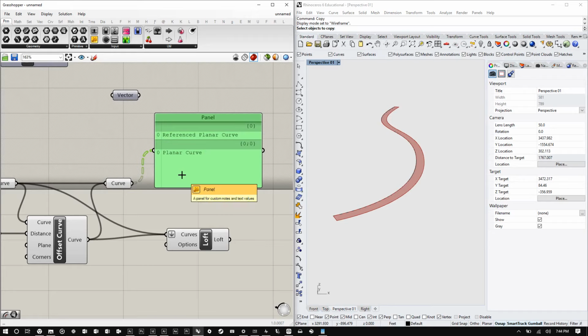And right now they're in a grafted state. So all data trees can either be grafted, which means each object is being treated as a separate individual object, or they could be in a flattened state, which means both objects are being considered as part of one tree, and they will act together as one.